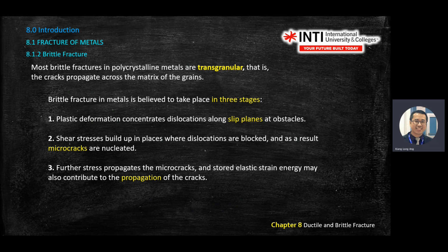Okay, so you start from plastic deformation, concentrated on a defect. There's a defect on the slip plane. So there's a defect inside here. Then it starts to form into a micro crack. A micro crack will turn into a crack. This one is a micro crack. This line is a slip plane. Then this one is a crack, or it becomes 2 bodies already.